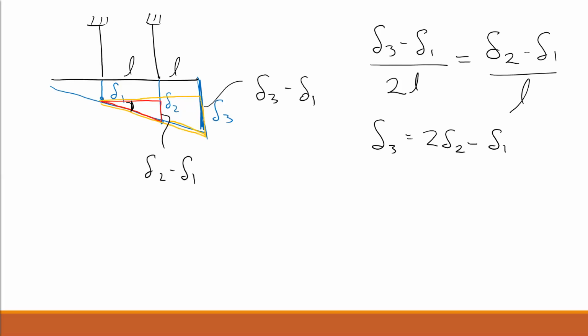Yes? For the similar triangle, could we not use from the farmost left point to L1 as our beginning? So could you use this? Yeah. The problem with that is that you don't know the displacement of this end. You don't know where that goes. All we know are the displacements of the 2 ropes.